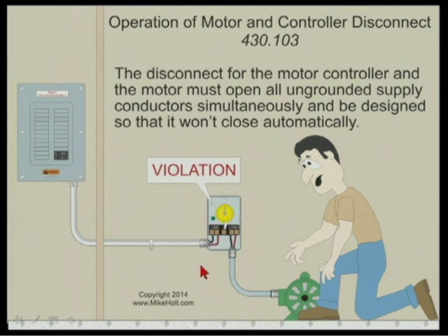Well, if you're going to use your time clock, it's possible a time clock could serve as a disconnecting means and could also serve as a controller. There's a possibility. But you might have time clocks that you can't turn off, or you turn it off, and then you go in to work on the motor, and then the time clock turns it back on again. So just be careful.